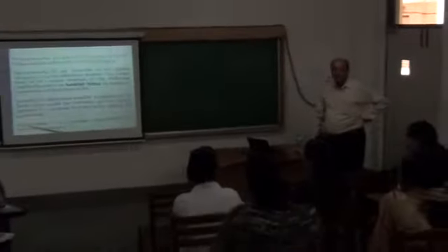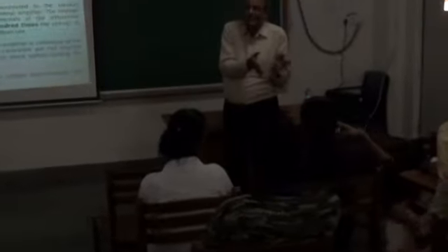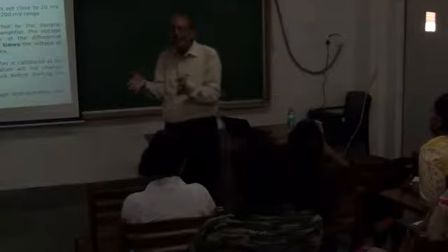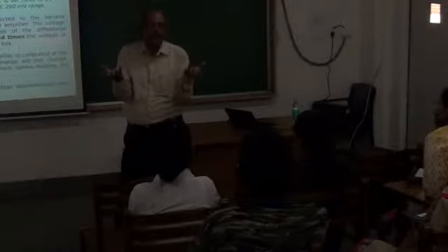In this case, you have neglected the internal resistance of the transistor. In which case? Making the DC amplifier. No, the DC amplifier is basically made by using... In fact, if we start from the beginning, normally once the transistor discussion is over, then we discuss transistor amplifiers, then the DC difference amplifier. So in the DC difference amplifier, if we want to have a very good common mode rejection ratio, the two transistors must be the same in all respects.